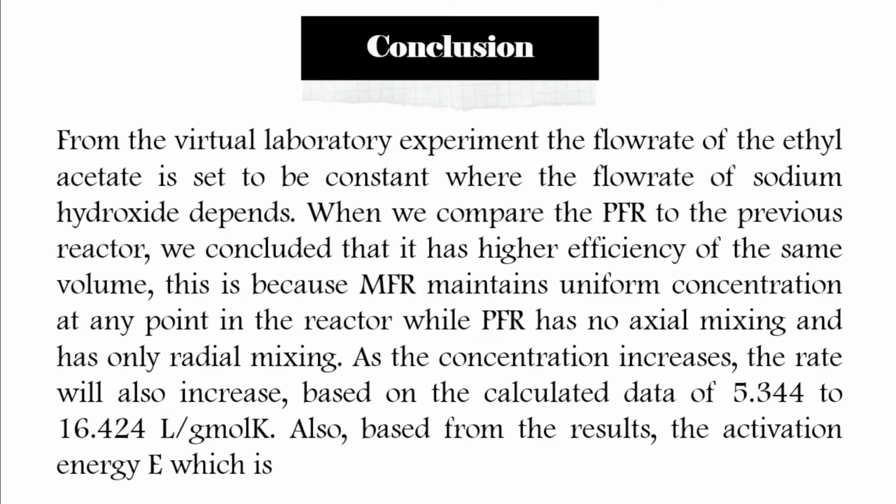For our conclusion from the virtual laboratory experiment, the flow rate of the ethyl acetate is set to be constant, while the flow rate of sodium hydroxide depends on it. When we compare the PFR to the previous reactor, we concluded that it has higher efficiency for the same volume. This is because the MFR maintains uniform concentration at any point in the reactor, while the PFR has no axial mixing and has only radial mixing. As the concentration increases, the rate will also increase based on the calculated data of 5.344 to 16.424 liters per gram mole Kelvin.